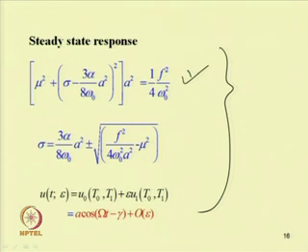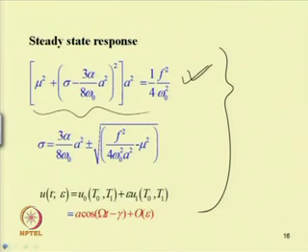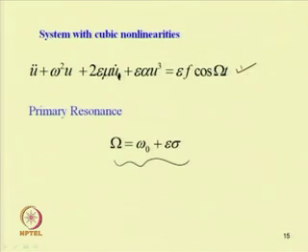So, one has to solve this equation which is 6th order in terms of A or quadratic in terms of sigma to obtain the response of the system. So, let us develop a MATLAB code to find the solution of this equation. Also, we can directly solve this equation by using the RK4 method or Runge-Kutta method to find the response of the system.